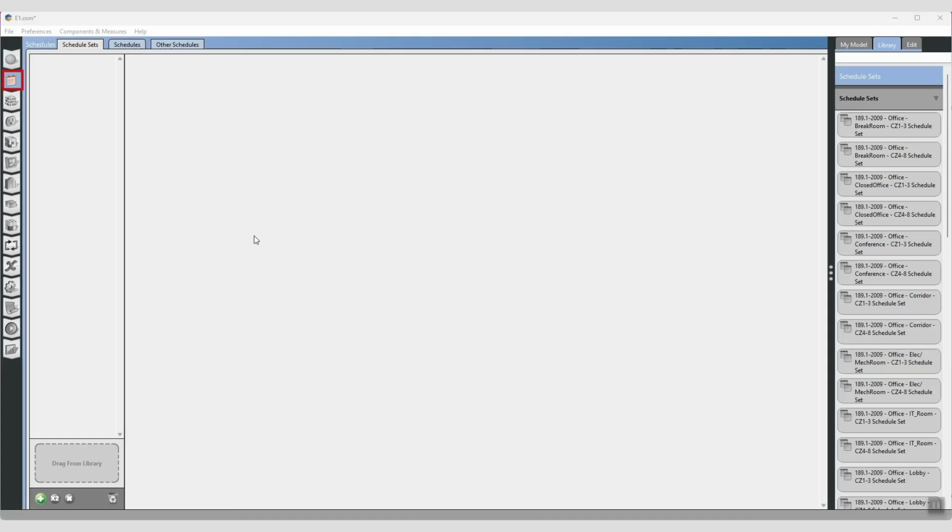Take a look here in the OpenStudio application. You'll see buttons to create a new schedule set with the plus button, duplicate an existing one for editing, delete sets you don't need, and even a purge unused button to clean up any schedule sets that aren't being used in your model. It's great for keeping things tidy. The Schedules tab has two main sub-tabs. The one we're focusing on now is the Schedule Sets sub-tab, where we define collections of schedules that apply to a particular space type.